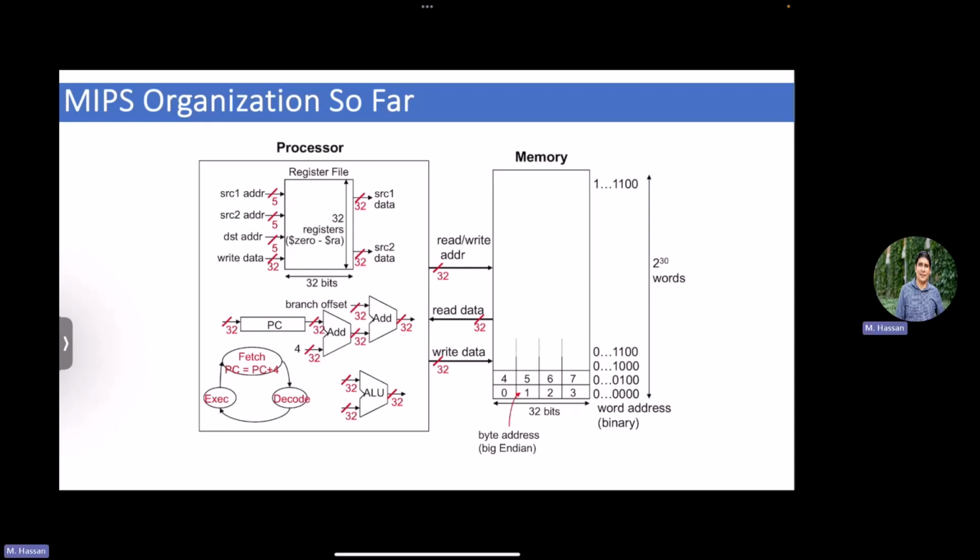Okay. Here, we discussed the arithmetic operations, the control flow ones, and the logic ones as well. And we also discussed the memory operations, right? The memory deals with the memory, that's why there is the interface between the processor and the memory. So you have load and store, and there are load word, store word, load byte, store byte. Usually when you go to the memory, it's 32-bit because your register is 32-bit, so the address is 32-bit. And you have the read or write address.